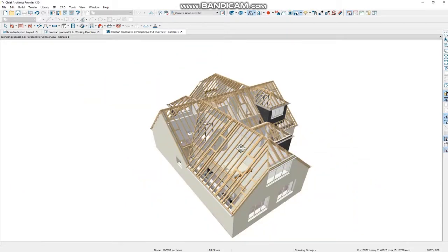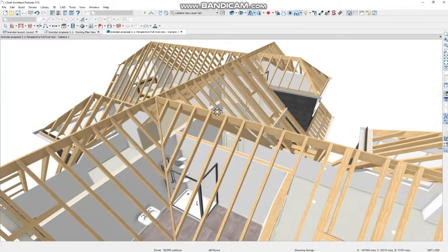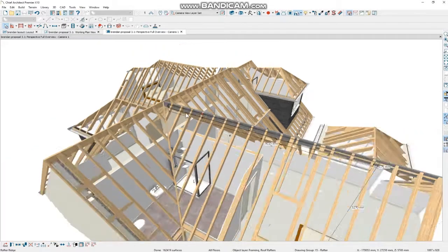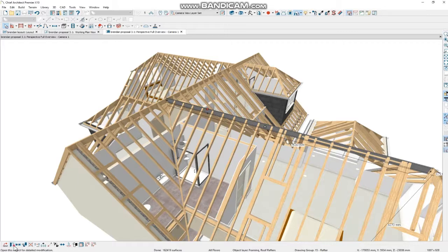And you can also add components. I mean, just a quick example, this job doesn't need a ridge beam, but so many do, and just for example, if I wanted a ridge beam, I would open that. In the general tab, I would go down to steel I, change the material to something that's flat and non-reflective. There's a steel ridge beam. It's a bit thin, so that's going to be probably 102, I would have thought they usually are, by 178.